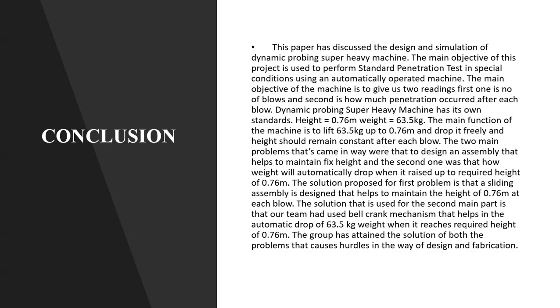So the conclusion of our research is that this paper has discussed the design and simulation of a dynamic probing super heavy machine. The main objective of this project is to perform standard penetration tests in special conditions using an automatically operated machine. The main objective of the machine is to give us two readings. The first one is the number of blows, and the second one is how much penetration occurred after each blow.